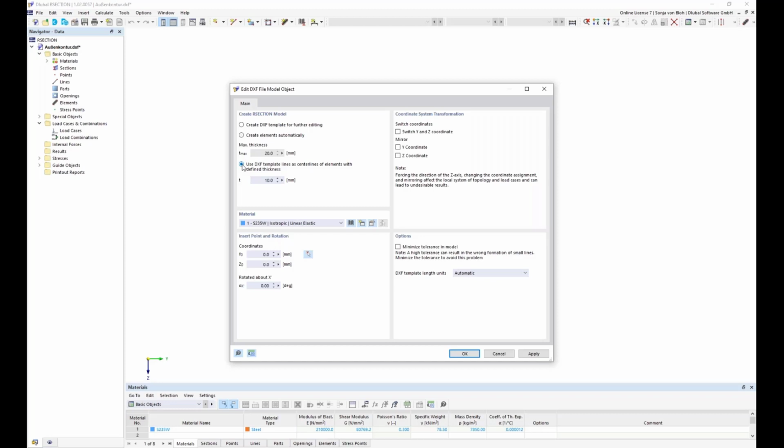Elements are required for the calculation using the thin-walled analysis and for the calculation of the effective cross-section, since only then the subpanels are available. The subpanels are required for the classification and calculation of the effective cross-section. If no elements are defined, the cross-section is treated as a class 3 cross-section in the design add-ons.